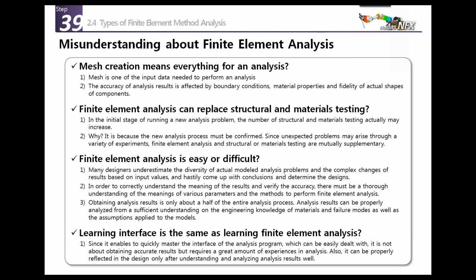Finite element is easy, not difficult. So many designers underestimate the difficulty of the modeling and the complex change of the result based on the input value. And they come very quickly with conclusion to determine the design, but this actually requires a lot of experience, like I told. So in order to correctly understand the meaning of the result and verify the accuracy, there must be understanding of the meaning of the various parameters and the method to perform the finite element analysis.